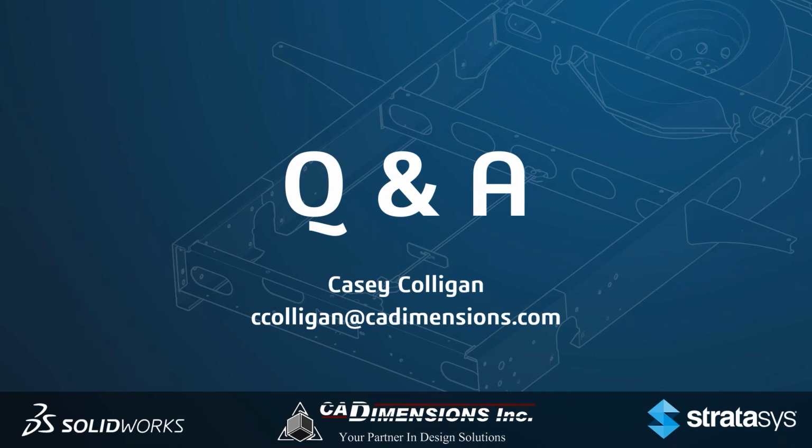Another question here, how do you load a model from SolidWorks into 3D Experience? So there's a couple different ways we can do this. There is one tool that I didn't dive into today called the SolidWorks connector, which basically is going to open up the space information. So when I was showing the 3D spaces, we can actually see all that information inside of SolidWorks.